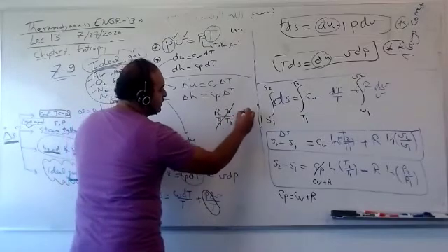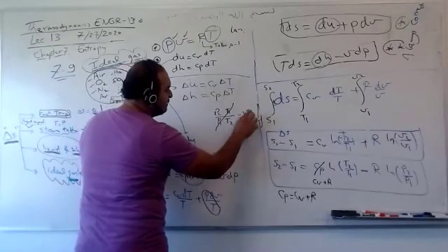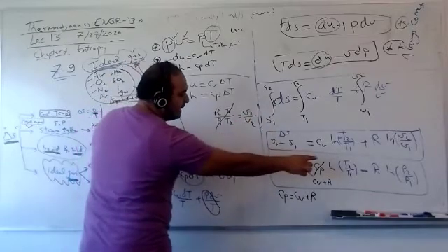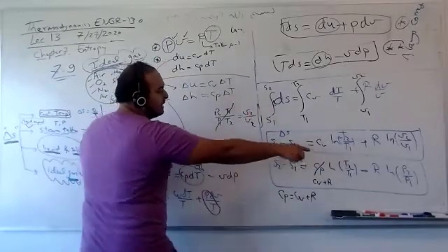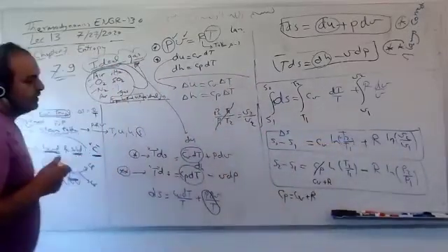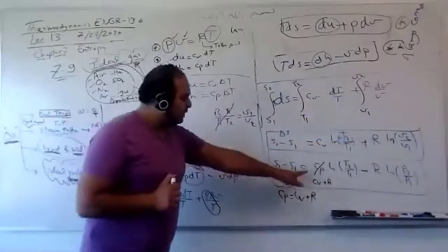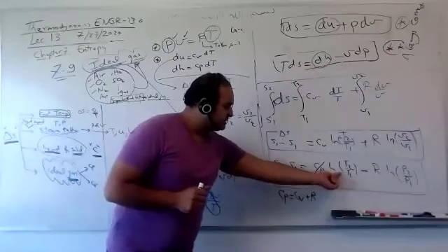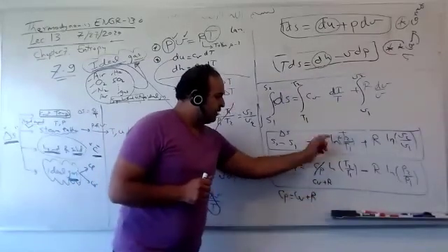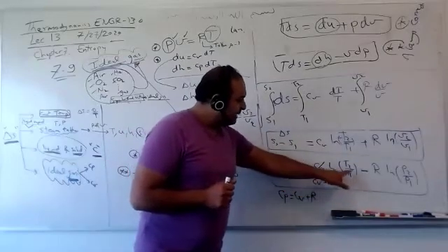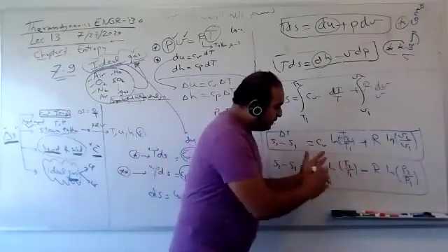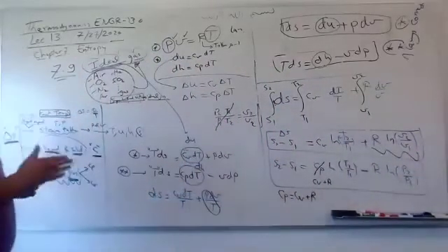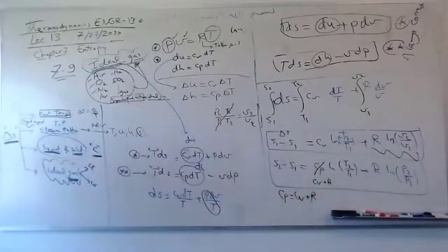This one is actually V1 over V2. Then to make it positive, reverse it, and you obtain this equation. So if you replace Cp equals Cv plus R, the first time this, the second time this minus this, if you combine together, it will be exactly this term. So this equation is identical for ideal gases.